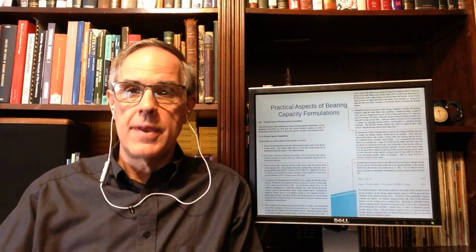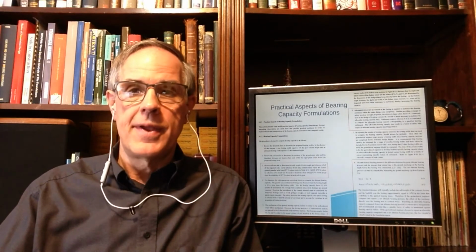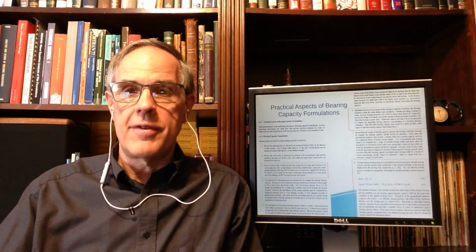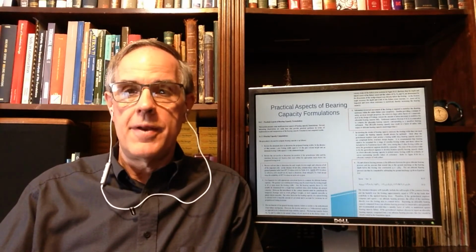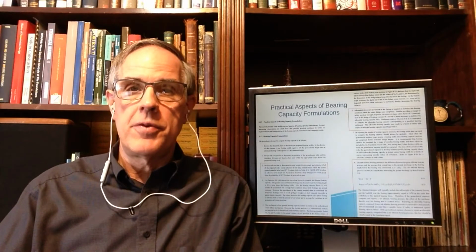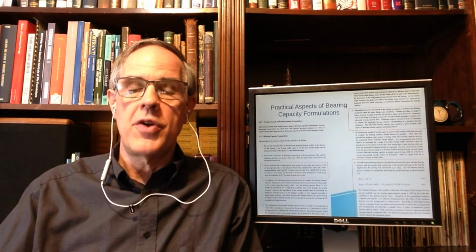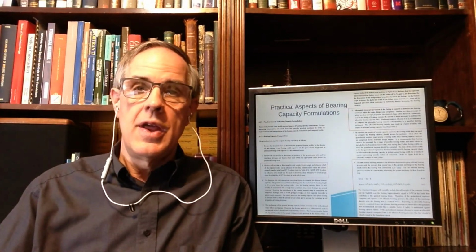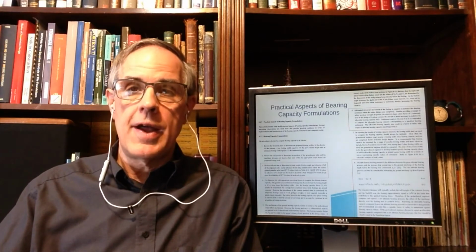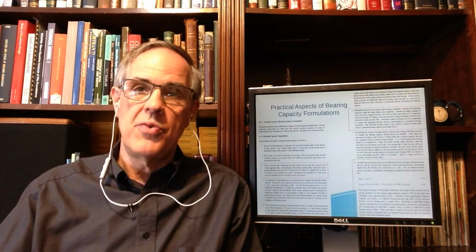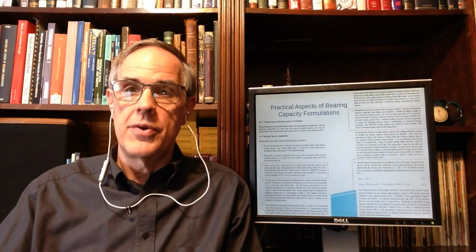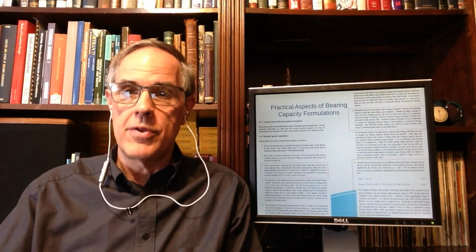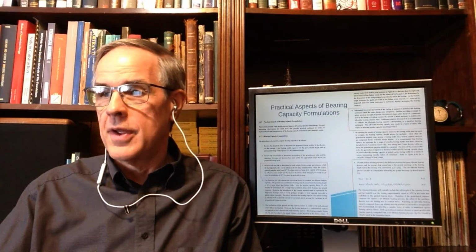Usually what you'll have, unless you really do well and get something like vane shear data, would be SPT data. SPT data must be reviewed carefully. With cohesionless soils, sandy soils, SPT data can be very reliable to determine properties such as unit weight, friction angle, and all that. Cohesive soils are a different story. You have to be very careful when you use them. So that's the first thing.